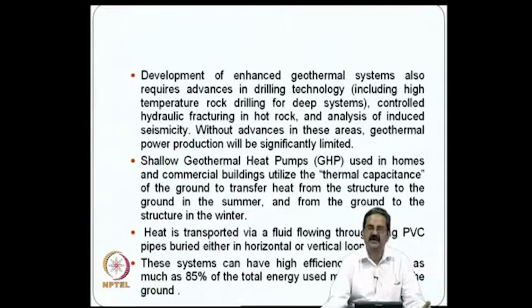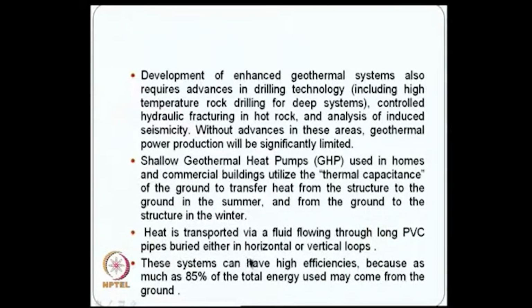stored energy. So, this is a concept, and this needs a big change in our ground improvement knowledge and thinking, and even foundations, the way that we design and all that. So, in most of the cases, the heat is transported via a fluid flowing through long PVC pipes buried either in horizontal or vertical loops.